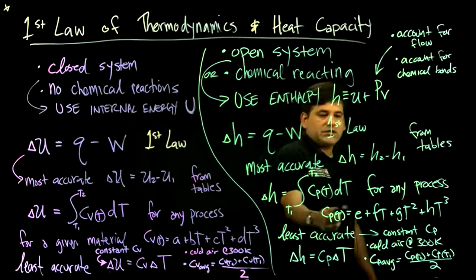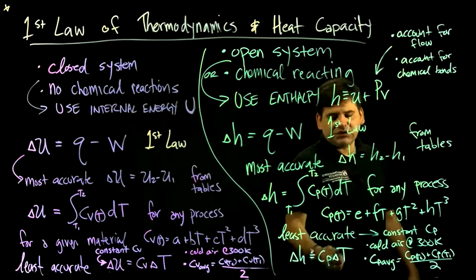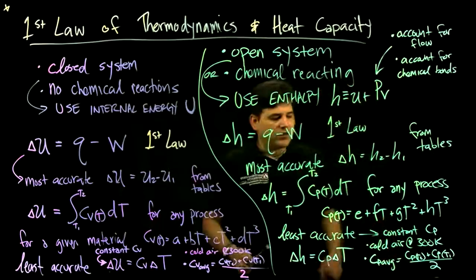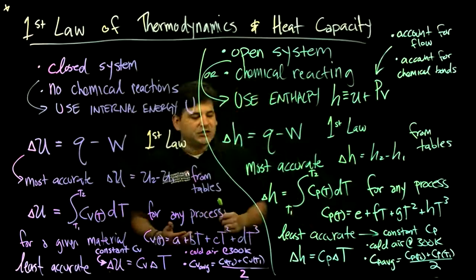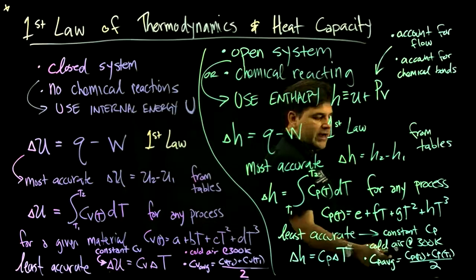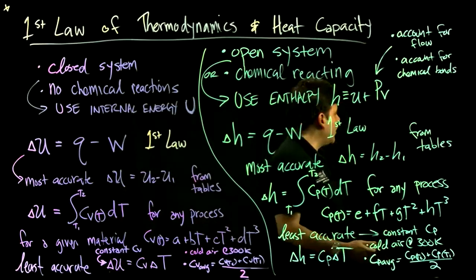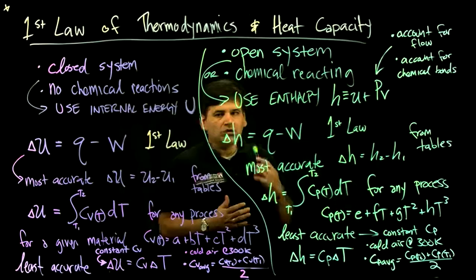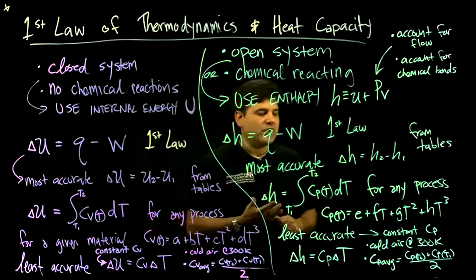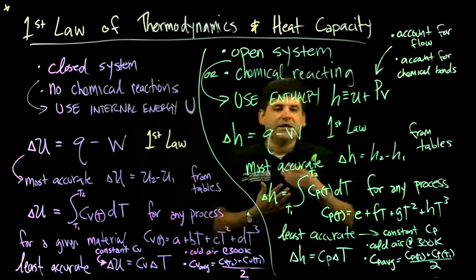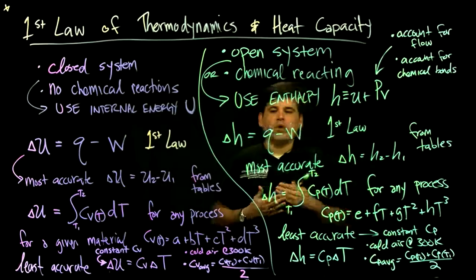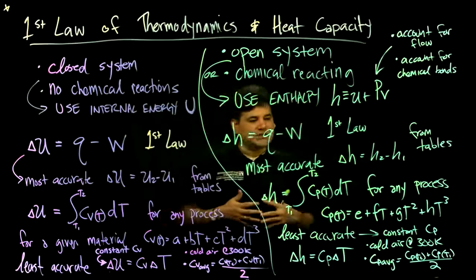You don't have to do this integral, and if you know the Cp, you can use it rather than a table. But in these engines, we use the cold air assumption, even though the engine goes to a very hot temperature due to the burning of the fuel. We still use it because we can get some nice equations to capture the physics.